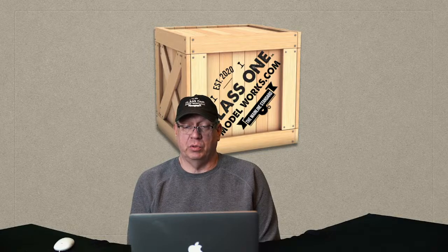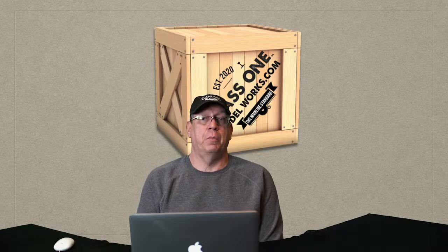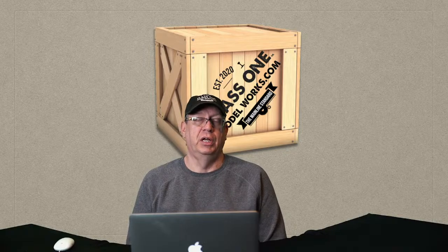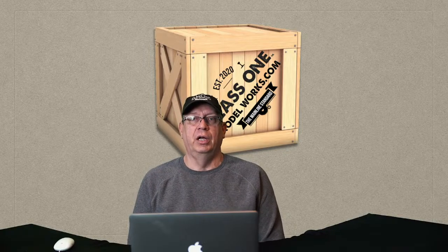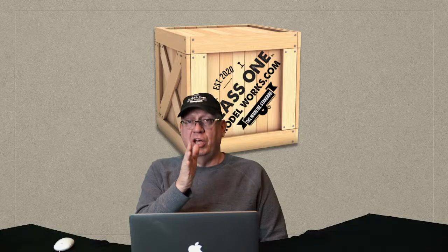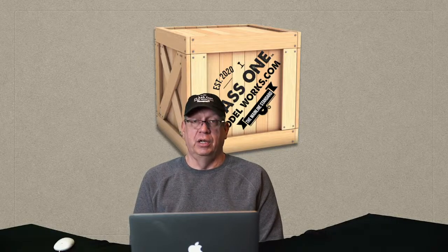How do people manage potential failures or system malfunctions? It was shown yesterday that there are some heaters for signals. Well, I'm going to assume you're talking about the model instead of the prototype, but the nice thing about building the modular system is, if you saw those cards that were like books lined up in there, those cards are removable and quickly programmable with some dip switches. So if you're having issues, something is not working, you can quickly swap out boards, reprogram them with the dip switches, stick them in. Oh, it wasn't that one. Until you find either the failure board or the section of your layout itself where you're having failures. And then you can quickly replace them. That's the beauty of the modularity of the system.